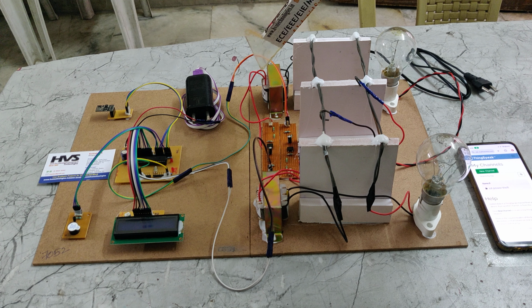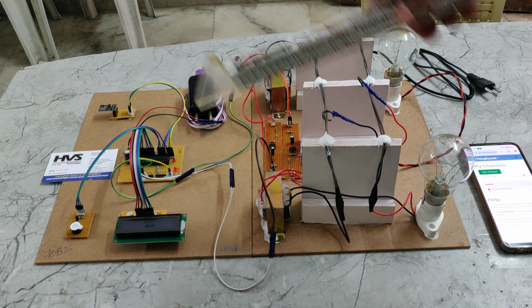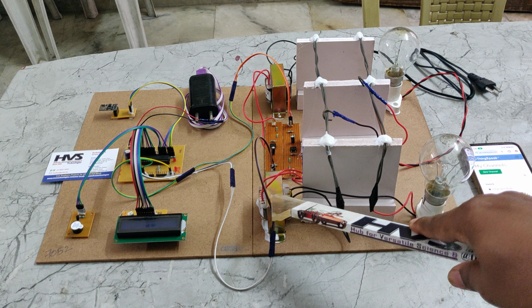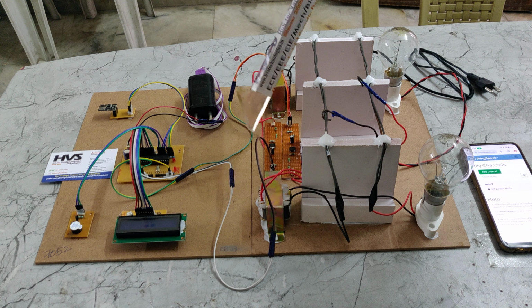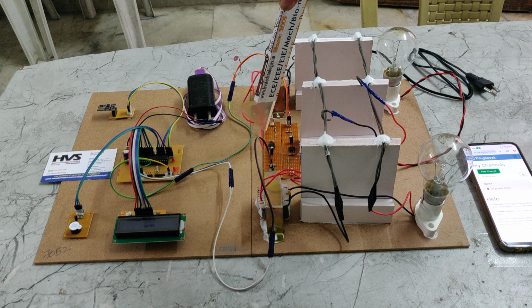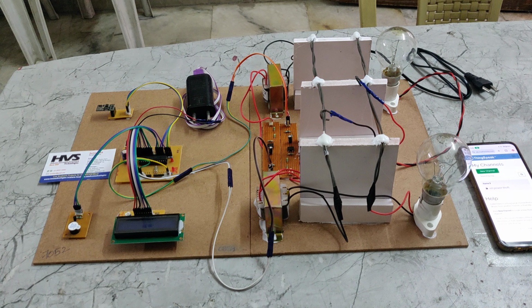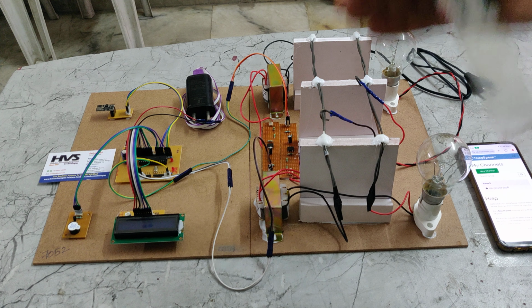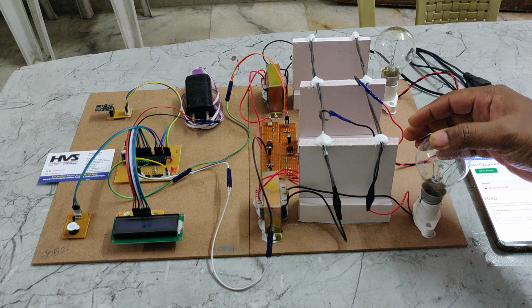The voltage is converted into DC voltage with the help of these potential divider circuits. As we know, the current transformer provides an AC voltage, and that will be stepped down and regulated to below 5 volts with the help of these potential divider circuits to provide the input to the PIC microcontroller pins A0, A1.